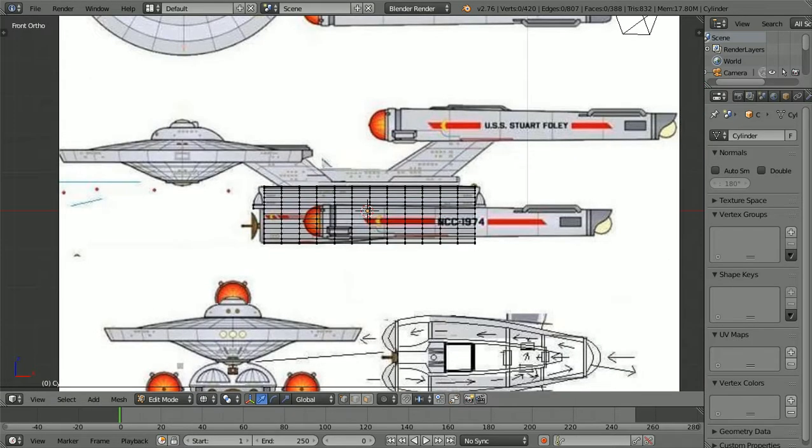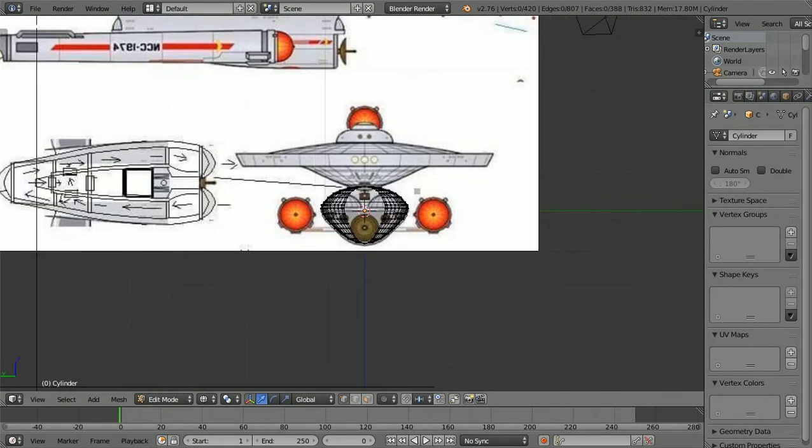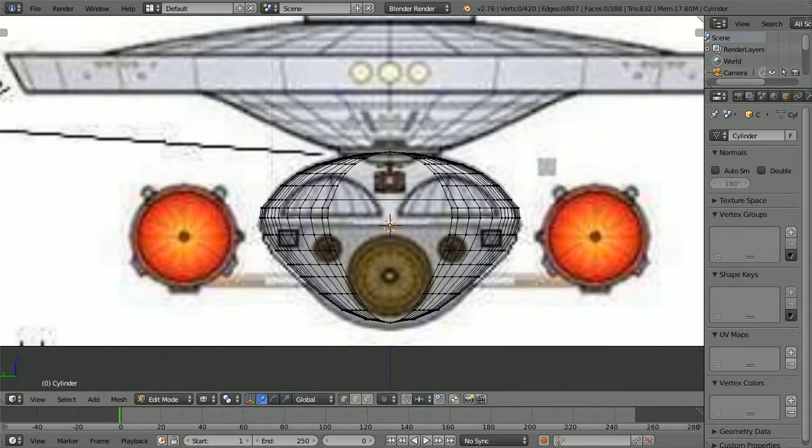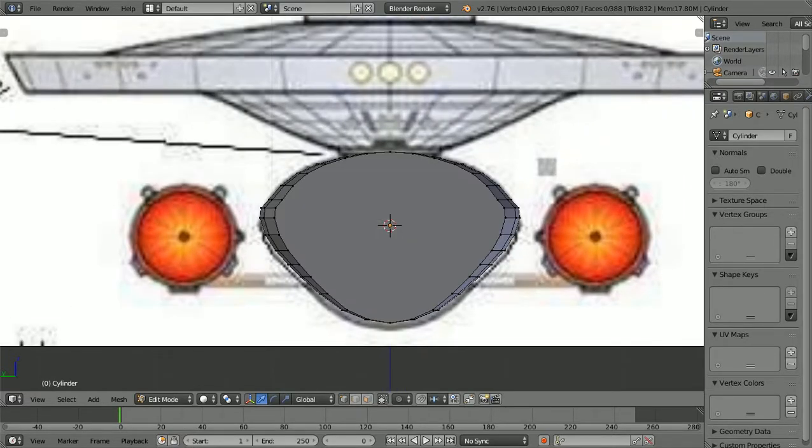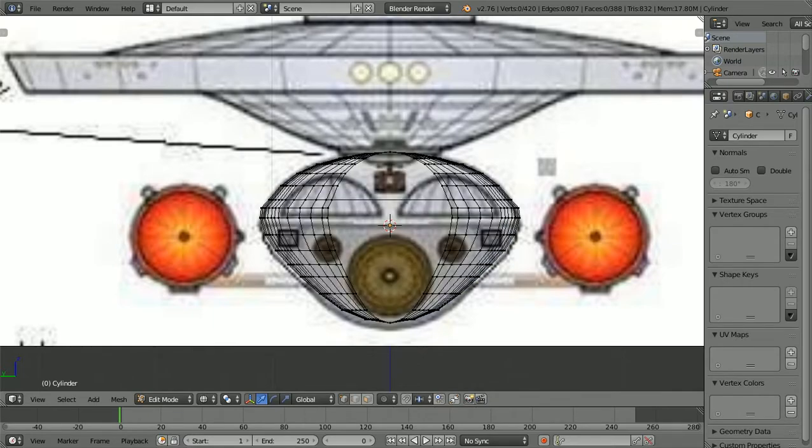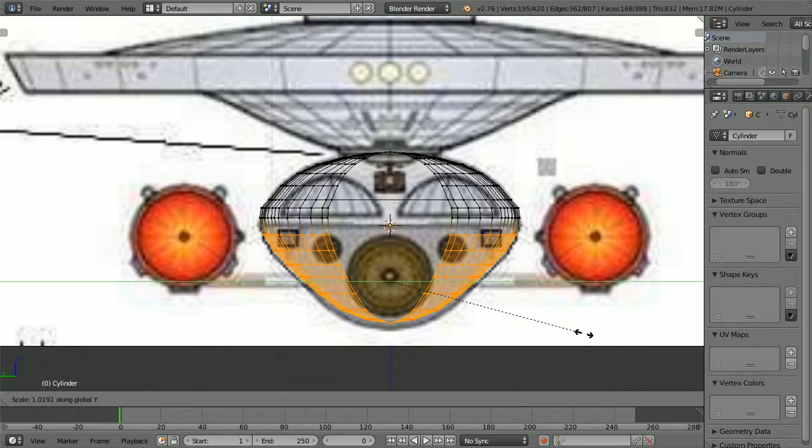And that more or less, now let's look at it from the front, which is actually Control 1. Okay, let's Z it in. Now see, if you noticed, what I did was by shaping that, it took some off the bottom, and by taking it off the bottom, it also distorted the shape. So I want to box this from the front. I want to scale it to the Y and fatten it out a little bit.